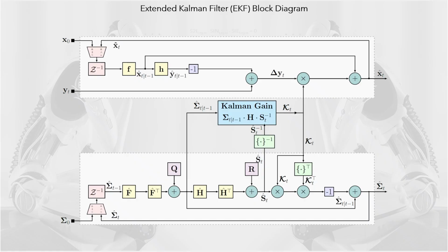The figure shows the extended Kalman Filter, EKF, block diagram. EKF linearizes the SS model, and it is a two-step procedure, prediction and update, where in each step EKF computes the first and second order statistical moments. Z-1 is the unit delay.